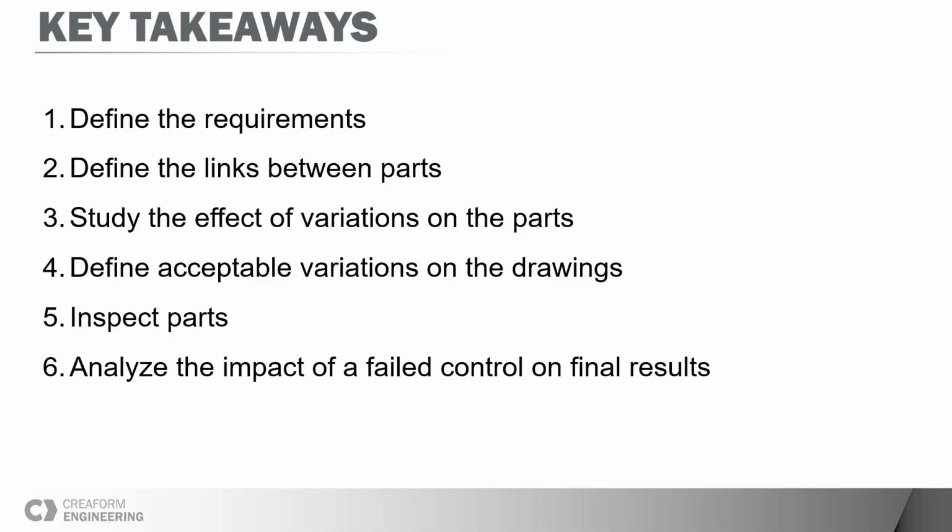Sometimes engineering is too severe, and they put tolerances that are so tight that it doesn't really make sense. It costs a lot for the company to manufacture, and their supplier will charge them more to be within these specifications, even though functionally you don't necessarily need that. Having the proper balance between your tolerances is something you get very experienced at by introducing GD&T and having feedback from your production. The more you do, the better you get at it, and the more feedback you get from every stage, the better you are at being effective and efficient.